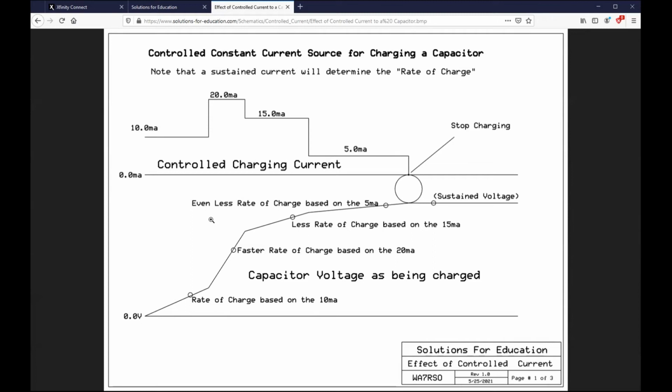As the current flows, it ionizes this material, but it also causes a deposit on one of the aluminum surfaces. And that deposit, which comes out of this electrolyte, causes that particular surface of the aluminum to become non-conductive, an insulator, but the other surface is still conductive.